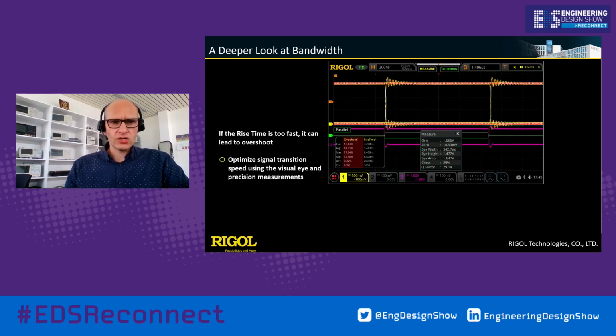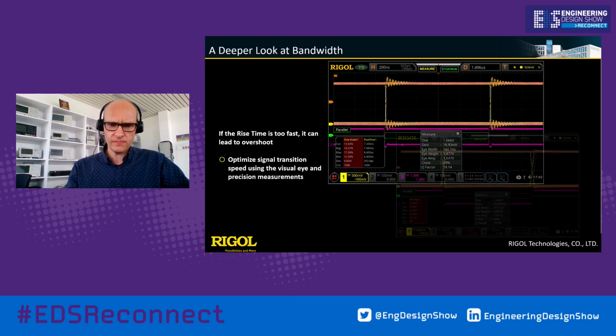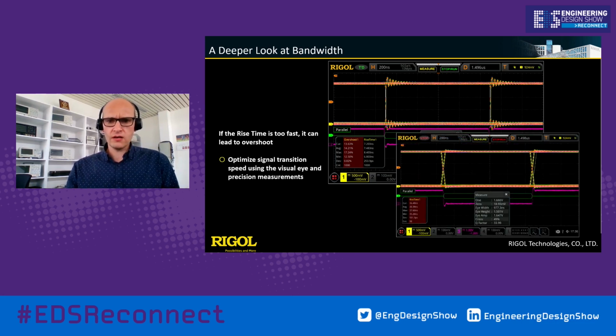Furthermore, it should be very clear, as I described previously in my speech, that if you improve the rise time of a signal, you can also generate overshoot effects, which could cause other problems in your design. Therefore, the compromise of rise time and overshoot should be fine-tuned during the design to avoid such effects.